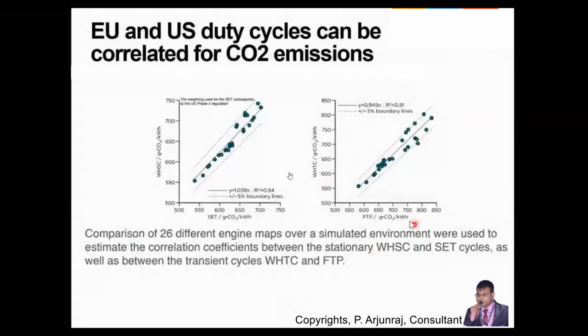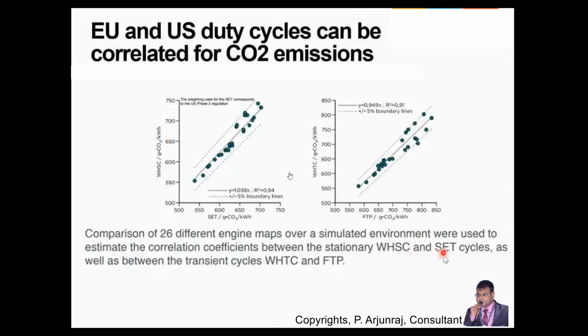I was mentioning WHSC, which stands for World Harmonized Stationary Cycle, and what I was telling about the central emission test cycle. Those have been mentioned here on the X and Y axes, considering the kilowatt hour, what is the consumption that we are going to experience. You can see the back-to-back comparison with respect to the World Harmonized Stationary Cycle and also the transient cycle. The comparison has been done with 26 different engine maps that have been simulated here,